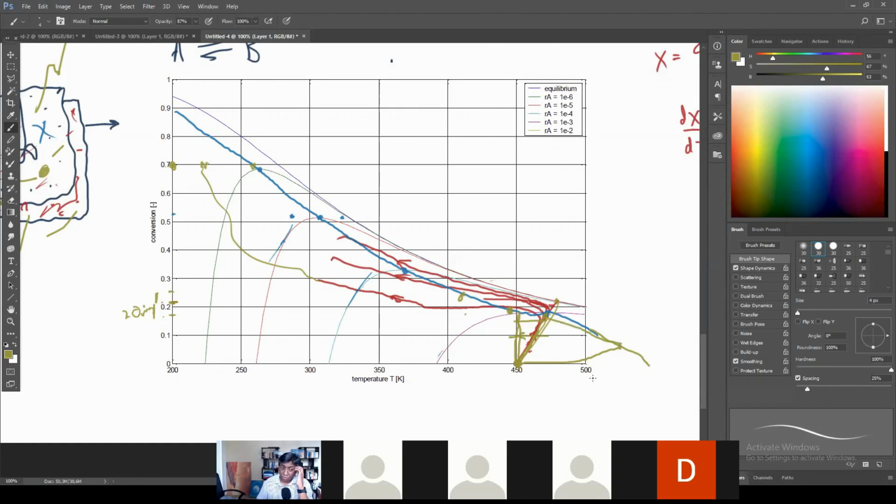And then it's an economic evaluation. Maybe it takes 1 hour if you just let it adiabatically get on the maximum rate line. Maybe it takes 20 minutes if you apply heating to get on there. That saving of 40 minutes changes your productivity in the day. It means you can run your reactor many more times, and so you can increase your productivity.